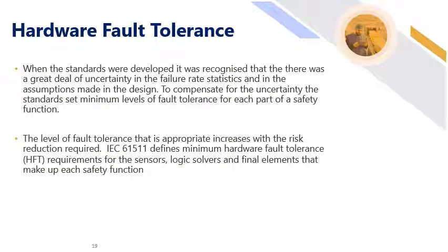One of the other main factors that we need to consider with the safety function is the hardware fault tolerance. Now, hardware fault tolerance is an identification of how much redundancy is needed to go with the function. So if a hardware fault tolerance of 0 is a requirement, then the function can be made up of just the single devices that the design requires.